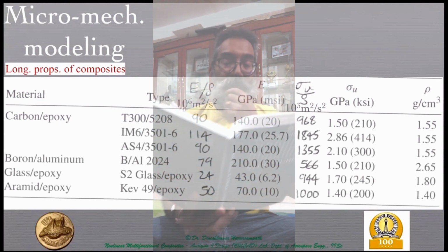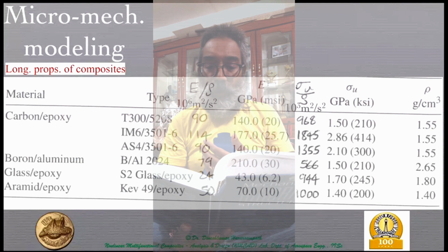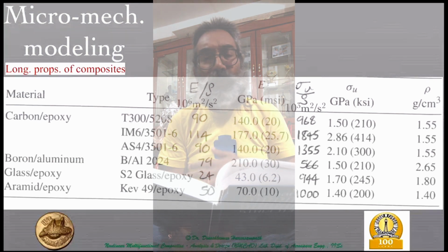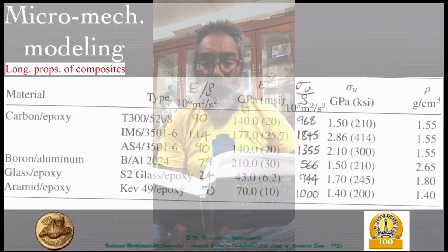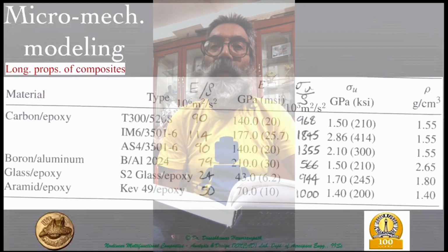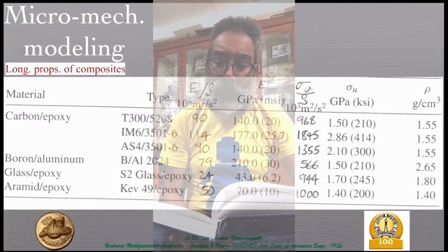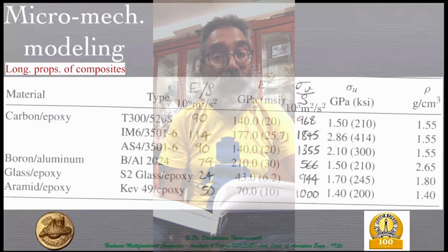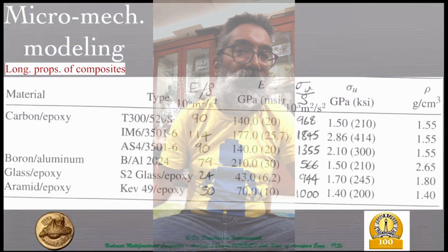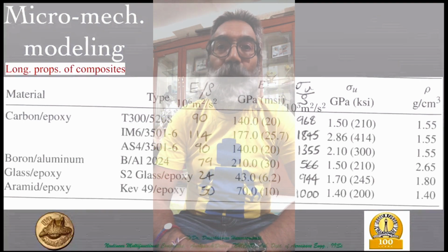There are also important alloys that are still being developed. One, for example, which is now already in place for some applications, is when you use lithium as one of the alloying elements along with aluminium, and there you would have an increase in the stiffness of about 10% and 10% lighter as well, because lithium is a much lighter element, as you know, appearing very early in the periodic table.